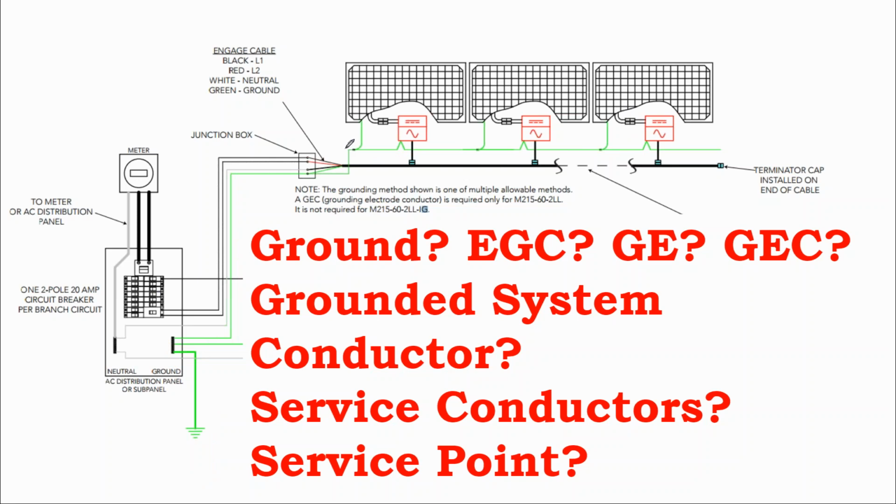Normally, that electricity would be flowing through the neutral back to the service panel. And then there's one point, and it can be inside the meter or it can be at the service panel, where this neutral wire is connected to ground, and that gives the electrons the ability to flow. And of course, your ground has to be actually grounded too.